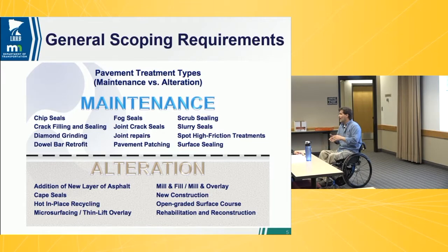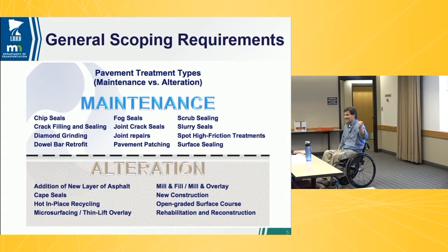But there are many entities who it appears aren't. And you don't have to be an expert ADA engineer to see that you've got a brand new road and a raggedy old curb ramp. Many users can see that. And they understand the requirements, and they say, why isn't such and such entity upgrading curb ramps? I would say do that at your own risk, because you're not going to have much of a case if you get called on it, because it's required since 2015, since earlier, but they reiterated in 2015, joint technical assistance from the Department of Justice and the FHWA, that these types of projects require curb ramps.